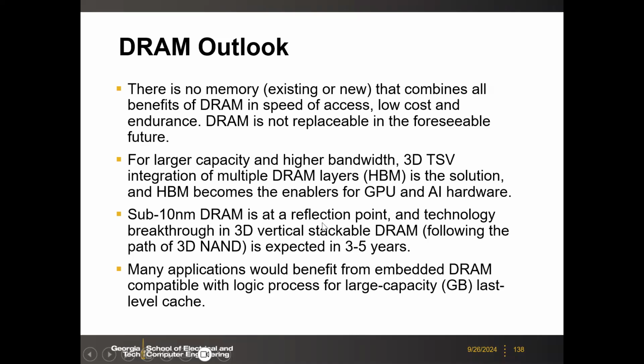That's why I say the DRAM industry is at an inflection point, because people are looking into the 3D vertical stackable DRAM as we discussed in the lecture. Or maybe there's an intermediate step, which is to switch from 6F square to 4F square by using the vertical channel access transistor with oxide semiconductors, potentially IGZO or other materials. This transition will happen, I believe, in the industry.